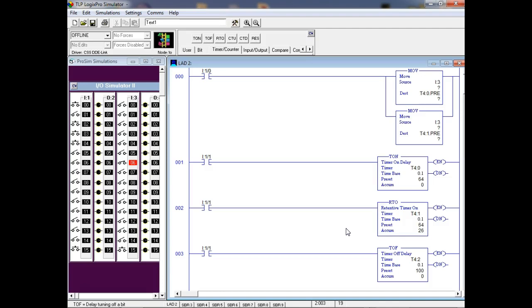Well, what you would do is you would cascade them. You'd have the first one, you would tell it to run forward. You'd bring in the run coils, right? And then on the timer off, you'd turn both the run coils off, and then the other timer you would switch on the reverse coils. So that's normally what you see cascade timers used for.